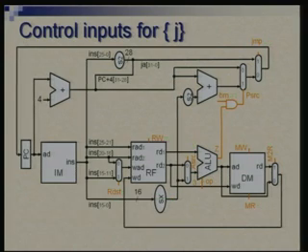Finally, we have this jump instruction. So jump instruction again does not require anything with RF, ALU, DM, all these are inactive. So RDST X, RW 0, ALU source is also X now. Since we are not using ALU, it does not matter what you give as input. MW 0, MR 0, M2R X, BRN is also X.